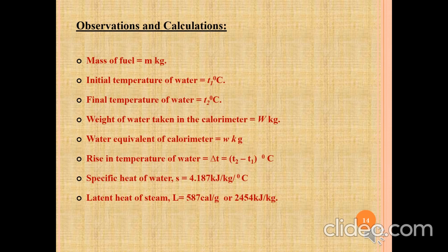So I'll explain what is that water equivalent of calorimeter. Whenever a fuel is burned inside the calorimeter, the heat is liberated. That heat is absorbed by the water jacket, but some of the heat is absorbed by the parts of the calorimeter. That constitutes the water equivalent of calorimeter, which is constant for a given calorimeter. That can be obtained by burning a fuel of a known calorific value.